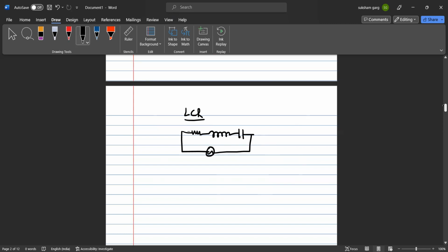Here we can smartly use a little vector diagram to come to the conclusion. How? The resistance offered by the resistor and current, both are in the same phase. So I'll write it here. Resistance offered by an inductor, I can write here as XL. Resistance offered by a capacitor, since it is behind, I'll write like XC. First thing, I will find the net result for XL and XC, which will automatically be in this direction, which I am drawing with a red color arrow, and it will be written as XL minus XC.